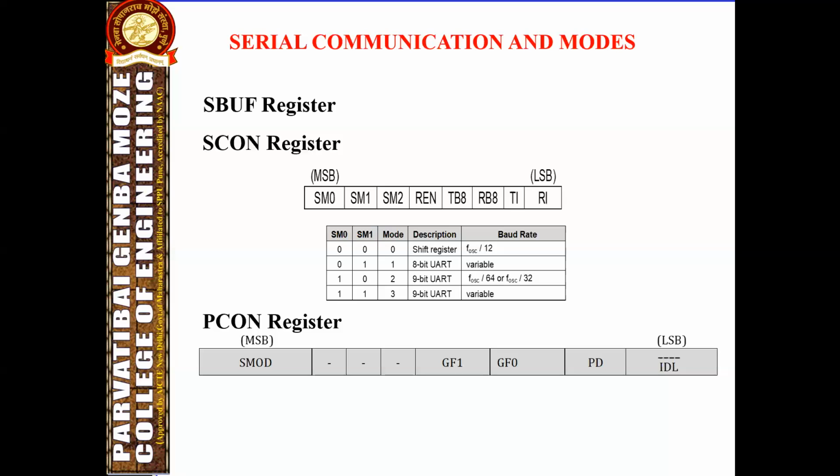Asynchronous serial communication peripheral chips and modems can be programmed for data that is 7-bit or 8-bit wide. While in older systems ASCII characters were 7-bit, in recent years ASCII characters are 8-bit. Assuming that we are transferring an 8-bit ASCII character using one start bit and one stop bit, there are a total of 10 bits for each character. Therefore, for each 8-bit character there are 2 extra bits, which gives 20% overhead.